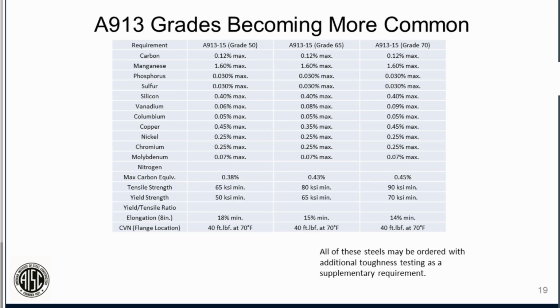So you'll have a steel with the weldability of an A992, grade 50, but the properties will be similar to a grade 65. So this is a pretty innovative way of using basically a modified heat treatment process. This is done while we're rolling, and impacts properties that gives us a much more ductile steel, a much more weldable steel, and with no more alloy content that affects the weldability of the steel.